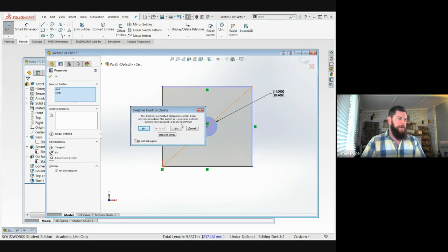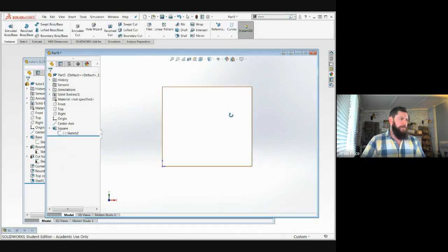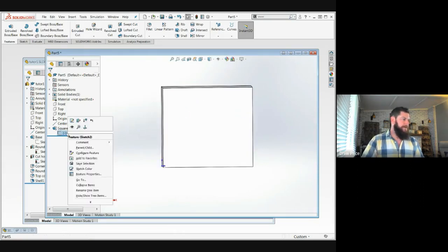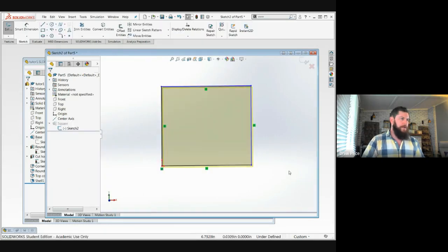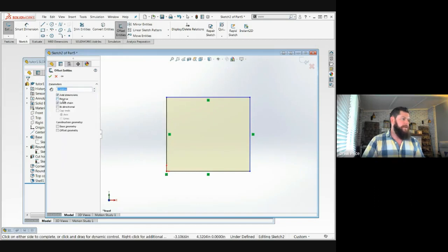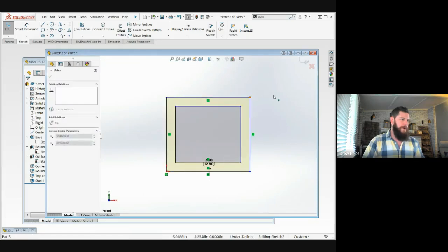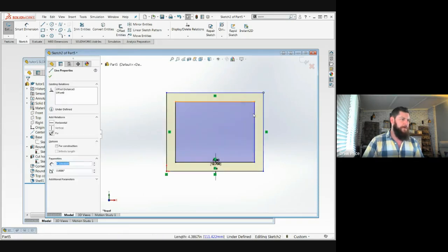So what if you wanted something like a plate with 4 holes that always stayed the same distance from the edges or something like that? Well, that's really easy to do in a similar fashion also. I can go into my box. I'm going to offset all of the edges. I'm going to reverse it so they go inside and say I want my bolt pattern to be offset a 1/2 inch from all the edges of my box. So now when I move those, the 2 offsets stay the same distance from each other.